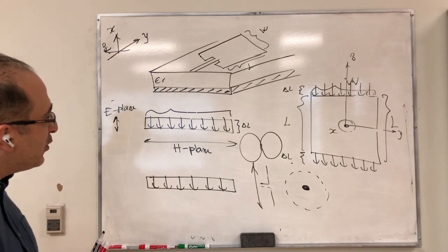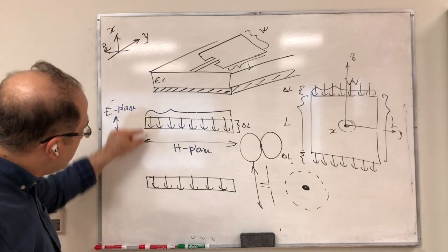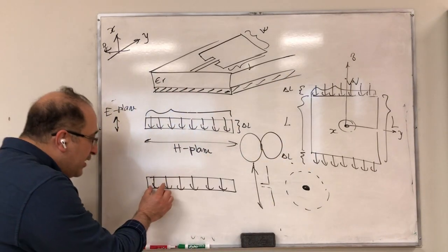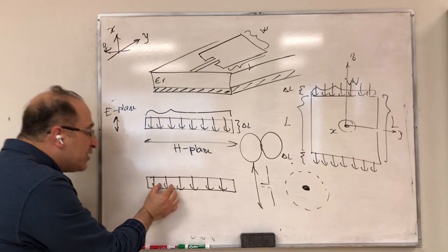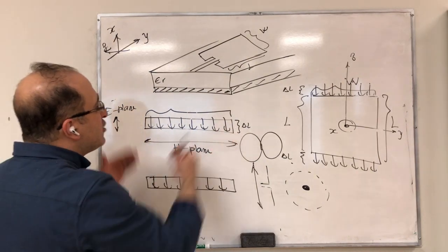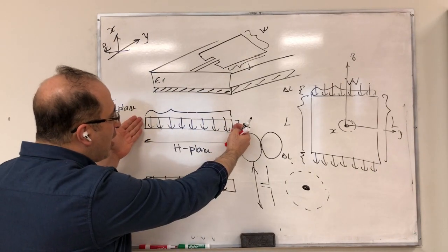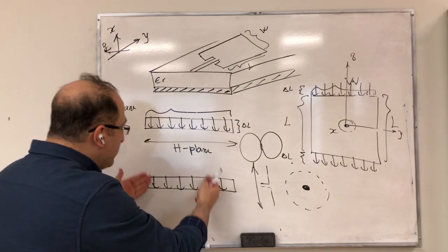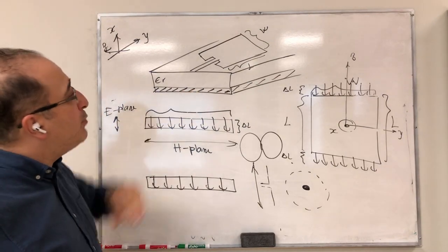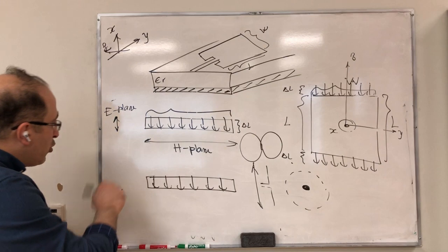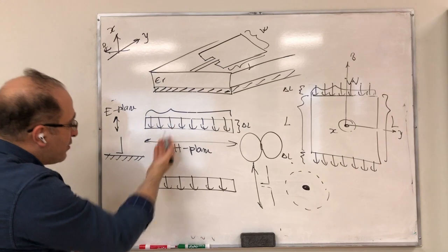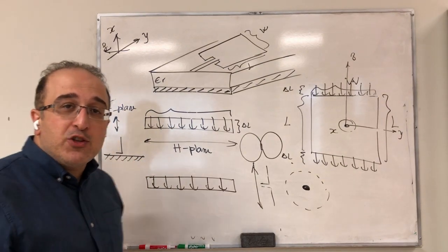We're going to talk a little bit about that. But my point here is that you can think of this as an aperture, and then you can think of their collection as a two-element antenna array. Each element of the antenna is essentially one radiating slot of the microstrip antenna. So you have a two-element antenna array, each of them like that. And also, it's backed by a ground plane. The same way that the monopole antenna was backed by a metal, now you have an aperture that's backed by a metallic ground plane.